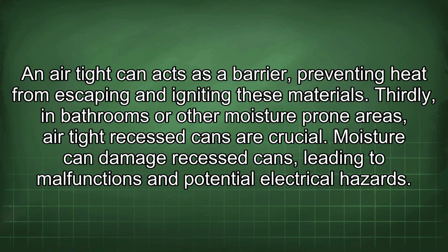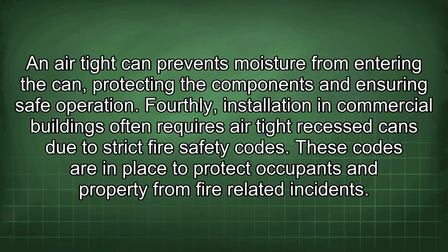Thirdly, in bathrooms or other moisture-prone areas, airtight recessed cans are crucial. Moisture can damage recessed cans, leading to malfunctions and potential electrical hazards. An airtight can prevent moisture from entering the can, protecting the components and ensuring safe operation.